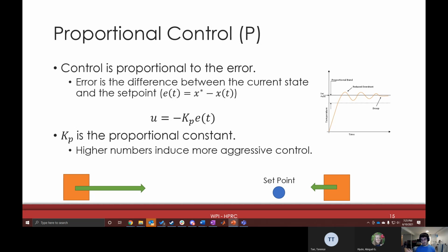And that's a relatively simple example, but if you just did proportional control there, you would take longer to get to point B. So different tools work best in different situations. Part of control design is knowing what control laws are applicable and then how to actually apply those. I will say, though, proportional control is very useful in a lot of cases.